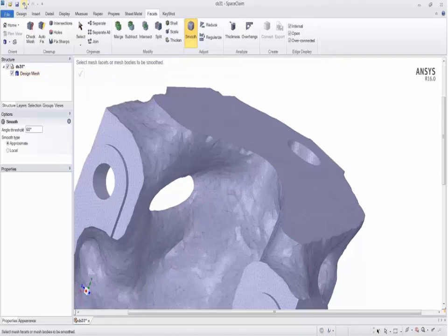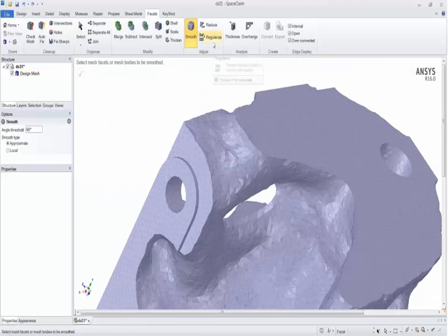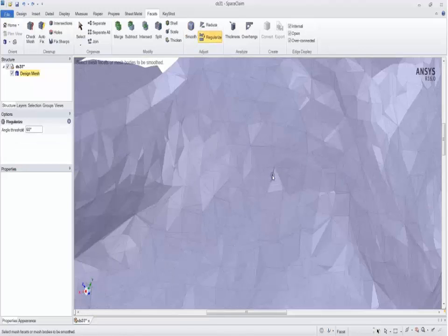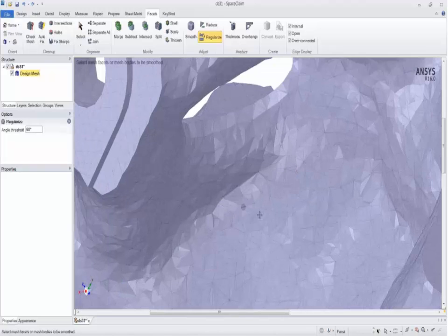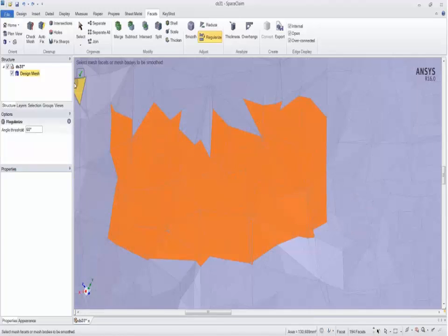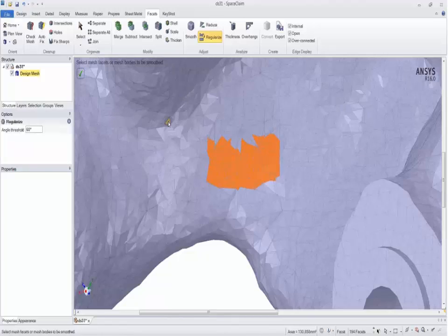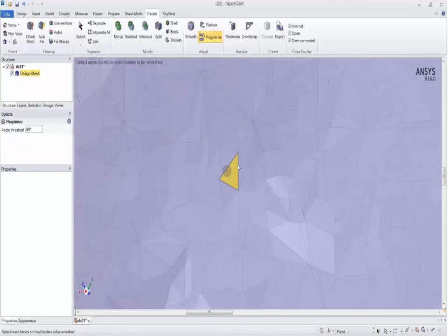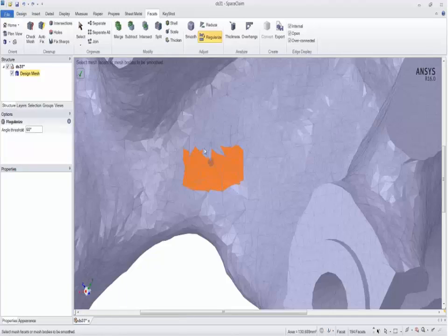It's a kind of remesh of your model, which is sometimes very nice for your model. And also another nice operation you have here is so-called regularize your mesh. For example, here you can select some triangles, for example, these parts. So now you see the mesh is not very nice. And after you just confirm, you have a better uniform mesh for what you have selected. So again, it is another nice option you can use here.